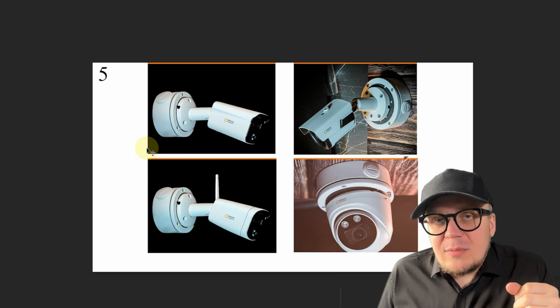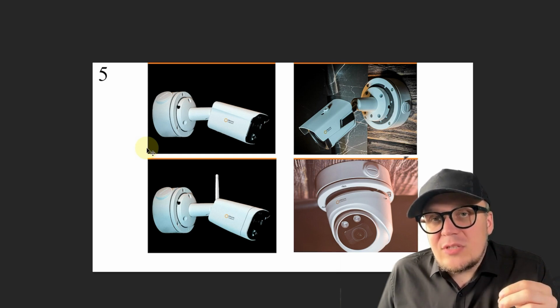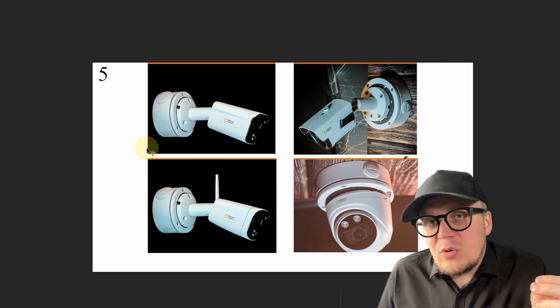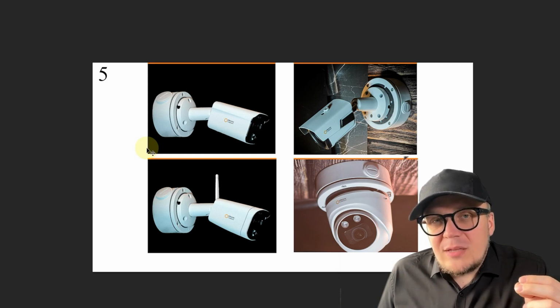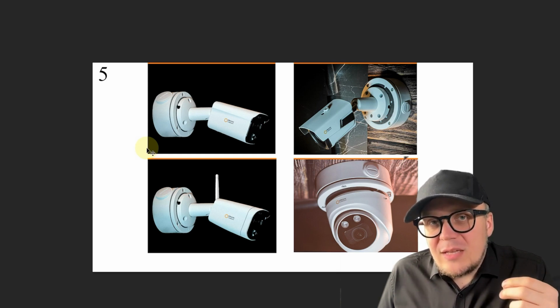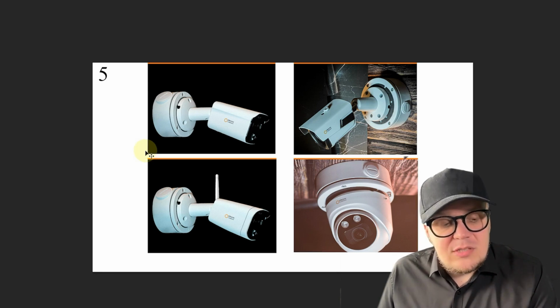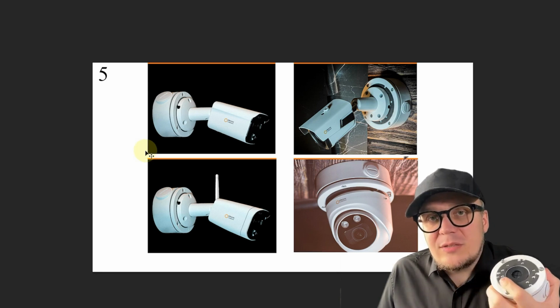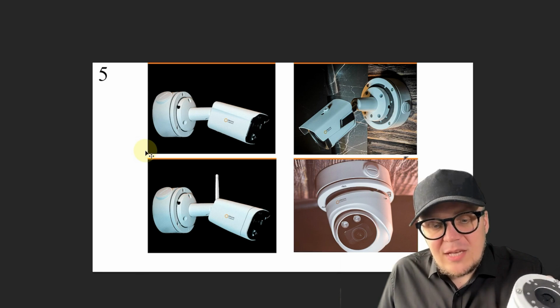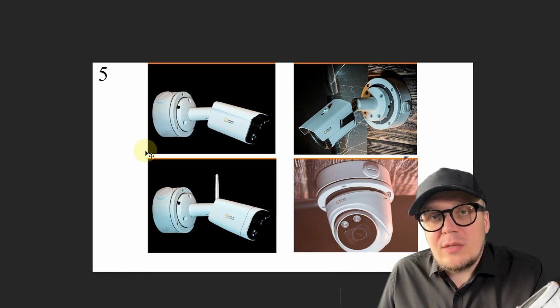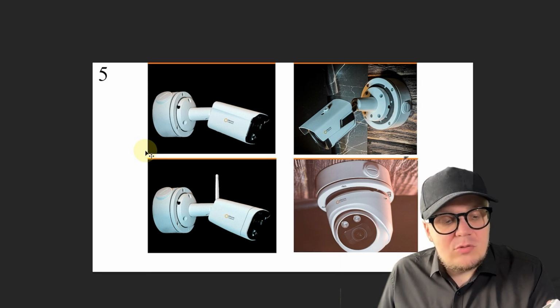And this is a mistake because after a year or a year and a half, due to humidity, the connector and the camera will start to oxidize. You'll throw it away and go buy a new one. A typical situation. First, the night illumination starts flickering, then it just stops turning on, and eventually the camera itself stops working. To prevent this, it is recommended to use specialized bases for mounting cameras. Here specifically, the camera I have in my hands is the ISON IP80QR. These are models of ready-made video surveillance systems.